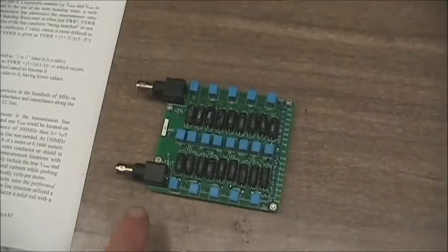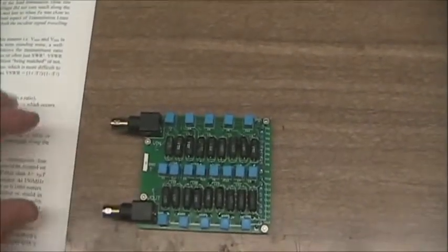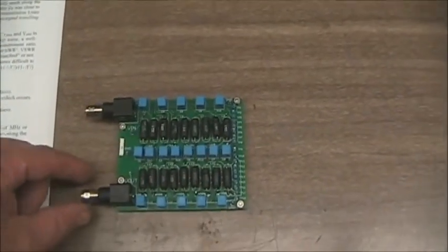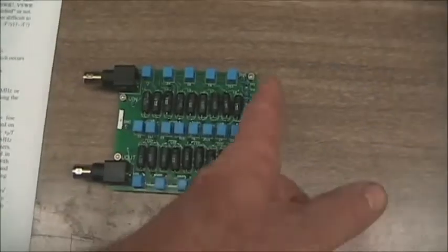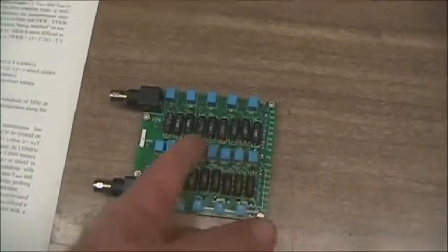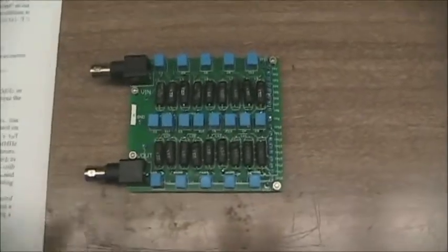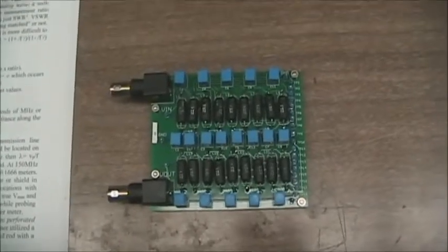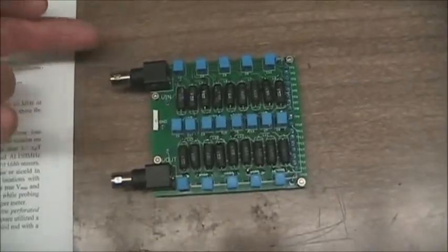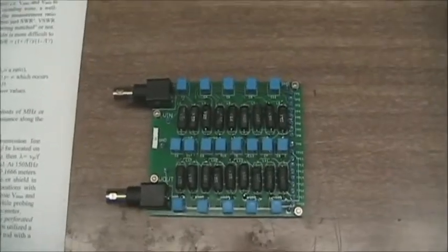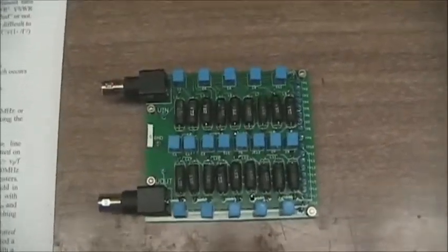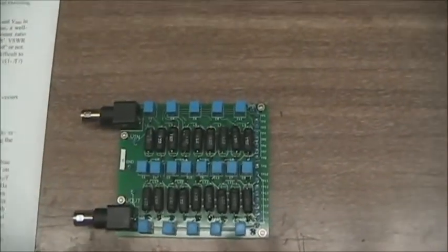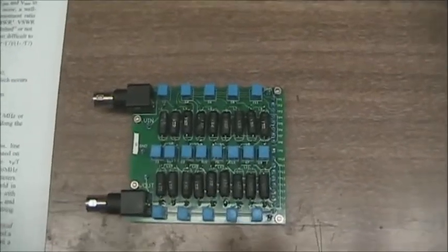A few weeks ago we did this laboratory where we connected a generator to this LC transmission line. We put a load on the end and we measured all of the voltage points along the line. There were 18 sections in there, and we set it up so that each section was equivalent to 10 degrees. We could do that because we had control of the frequency there. And then we saw how a voltage pattern was created associated with the transmission line, and it was to illustrate the reflections from the load.